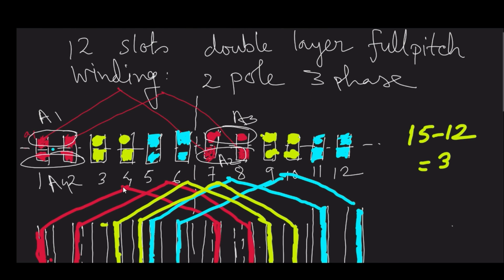See, this was a case of double layer winding. Even if we consider a single layer winding, the first one which I showed you, whenever your number of slots per pole per phase becomes greater than 1, your winding will eventually become a distributed winding. That is the paper model which I showed you in the last video, using some paper and loose conducting wires with insulated coating.